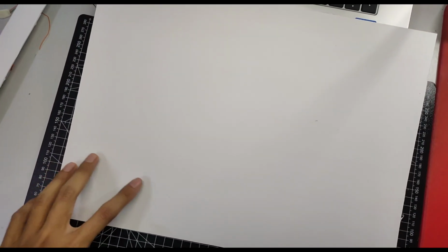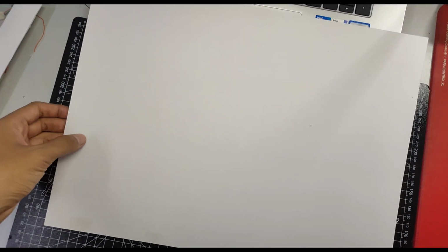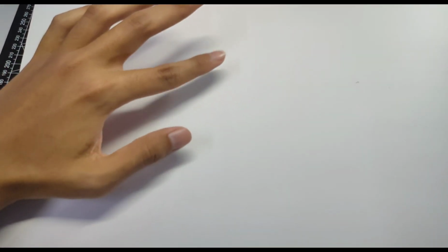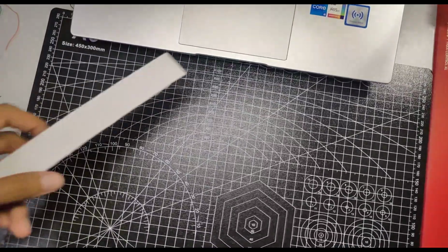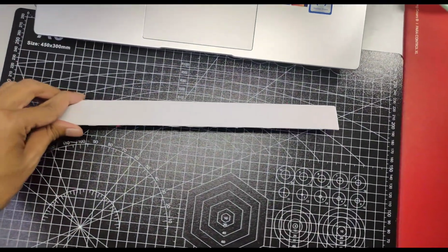Okay, now I explain the process to make the prototype. First, I prepare the components that will be used and I test each component to ensure that it is in good condition. And then we start with the prototype base. Here, we are using PVC foam. You can use any suitable material in this prototype. The size that will be cut for the prototype base is 29.5 cm for the length, and 3 cm for the width, and we use PVC foam 2 mm thick. The size will be around like this.